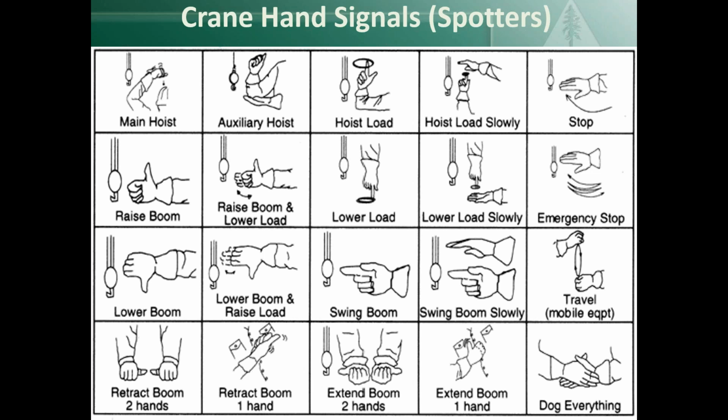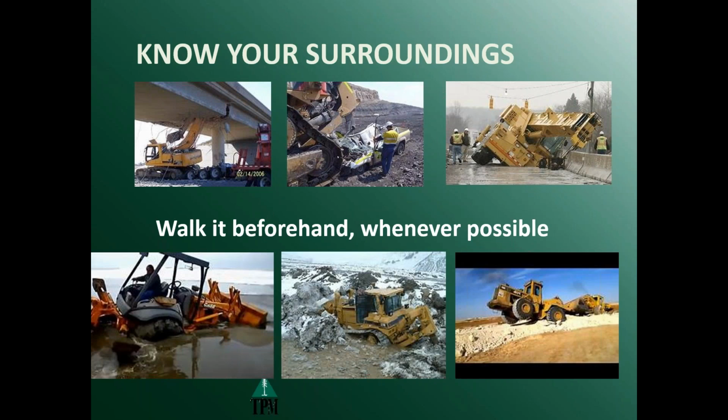or boom trucks. But really, my biggest advice, from being around heavy equipment for the last 25 years, is know your surroundings. I've seen really powerful, strong, impressive equipment get stuck because we didn't walk where we were going to be working. So if you can, walk wherever you're going to be driving the equipment beforehand. It gives you a sense of where it's muddy or soggy. We did have somebody sink a brand new off-road forklift up to the frame. They drove out into a field and immediately sank in. So if we're operating somewhere new, we want to walk it beforehand.